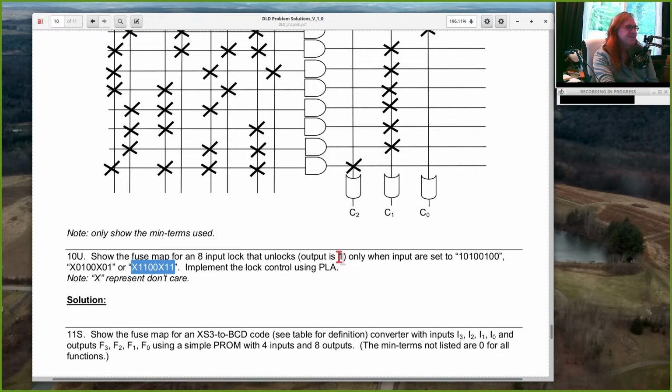So this is going to have a total of 8 inputs and 1 output. And you don't need to do a K-map for this. In fact, I probably wouldn't do a K-map for this, because K-maps of 8 inputs, we haven't done that. The most we can do with a K-map easily is a 4 input function, and this is an input with 8. But since we're only generating 1 output and it's only got to be true in 9 possibilities, we're only going to need to generate 9 product terms and OR those together.